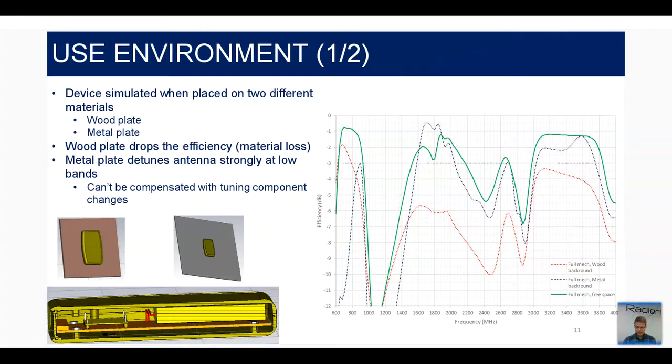And this is something that you cannot fix with antenna tuning itself. So probably the only way to get rid of this kind of effect would be to increase the distance from the device to the metal plate.